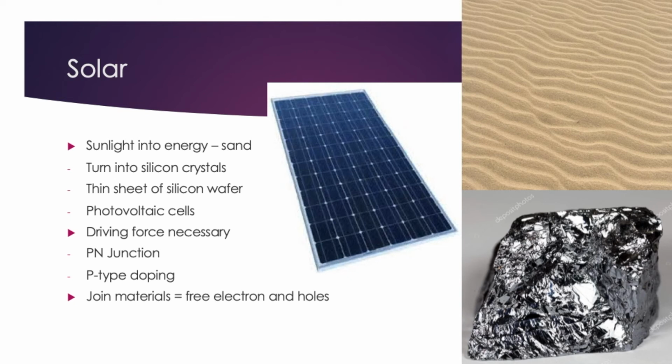When photons hit the n-type side, there is sufficient energy for electron and hole pairs to enter the depletion region. The electric field in the depletion region drives the electrons and holes out, leading the electrons to go to the n side, while the holes go to the p side. The concentration of electrons to holes becomes so high that a potential difference will develop between them. If there is any load attached between them, electrons will start flowing through the load. This leads to the solar cell continuously giving direct current.